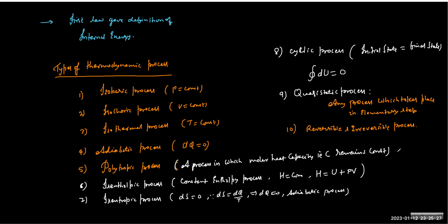And therefore, it is a very famous question: in a reversible cyclic process, the work done will be how much? And the answer is 0. Because the forward path is the same as the backward path, the area under the curve is plus and minus of equal value. So if you go by the path and you come back by the same path, the area under the PV graph is how much? Zero. For the upward journey, it is positive. For the downward journey, it is negative.